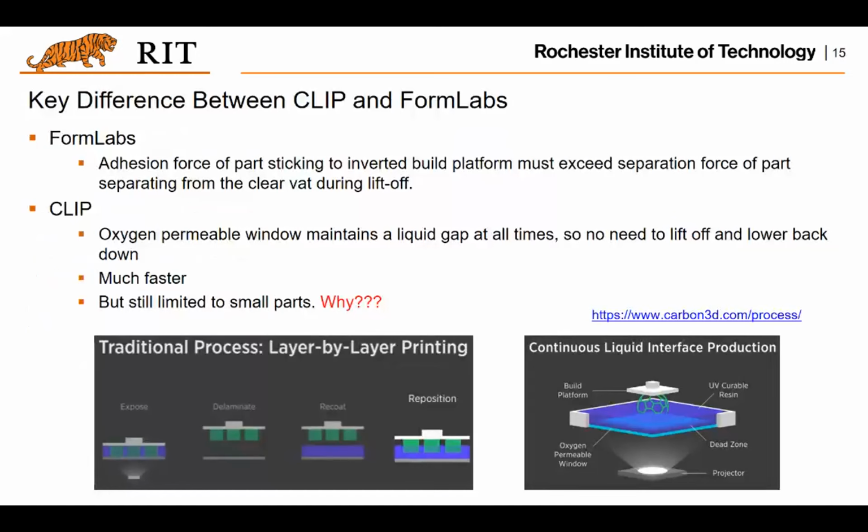But let's do a little comparison. Let's look at the key differences between the continuous liquid interface process and the Formlabs process. For the Formlabs process, the adhesion force of the part sticking to the inverted platform must exceed the separation force of the part separating from the bottom of the tank, right?